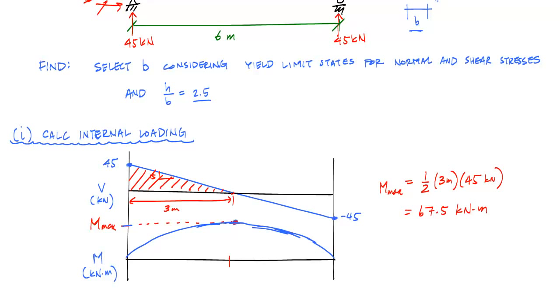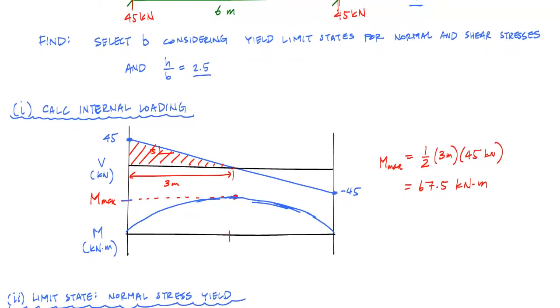The first limit state that we're going to look at is the normal stress condition. It doesn't matter; you can look at shear stress, normal stress, whatever, but you have to look at them one at a time. For each limit state there is essentially one basic design relationship, and some people call that a performance function. Here we're just going to start by looking at normal stress yielding.